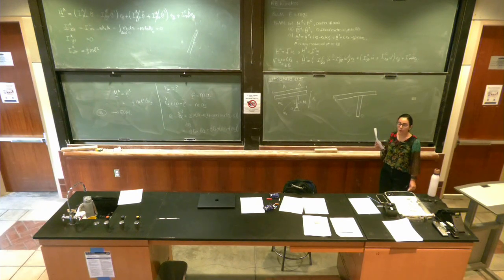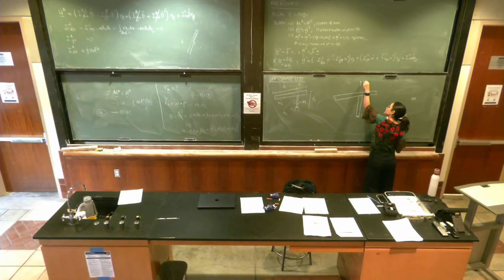Yeah, so what motions are constrained and what motions are not constrained? Yeah, it's only allowed to rotate along EZ, right? So I'm constraining translation. The origin, or the base of the bar, is not allowed to translate, plus rotation is restricted. Rotations about any axis other than the EZ axis are restricted.